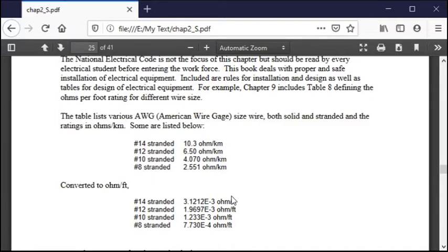So if you were to say, why do I need this? If you run a solenoid too far, the application at Owens Corning was always more than 200 feet, you needed to run a larger AWG wire gauge. From 14, you would go to a 12, because the inrush current was higher than the running current, or the settled current, of a solenoid. The inrush current would have to be high enough that the voltage drop at the solenoid wouldn't let it pull in. You'd say, you had to remember that? Well, usually we just said 200 feet or longer, you'd have to put a solenoid at a 12 gauge instead of 14 gauge. We knew some rules of thumb, but where did those rules come from?